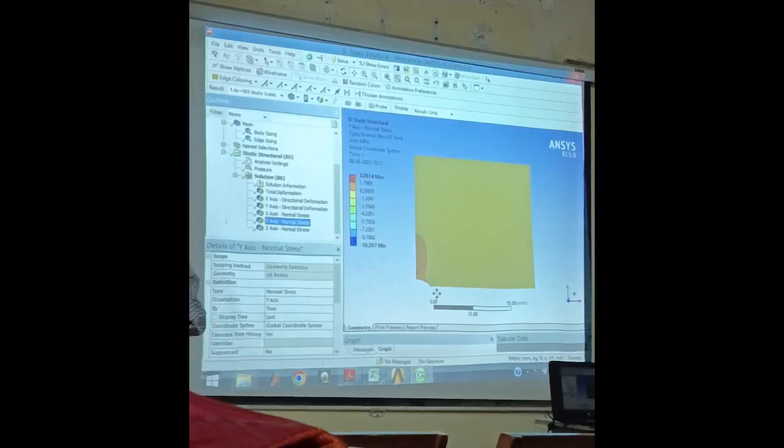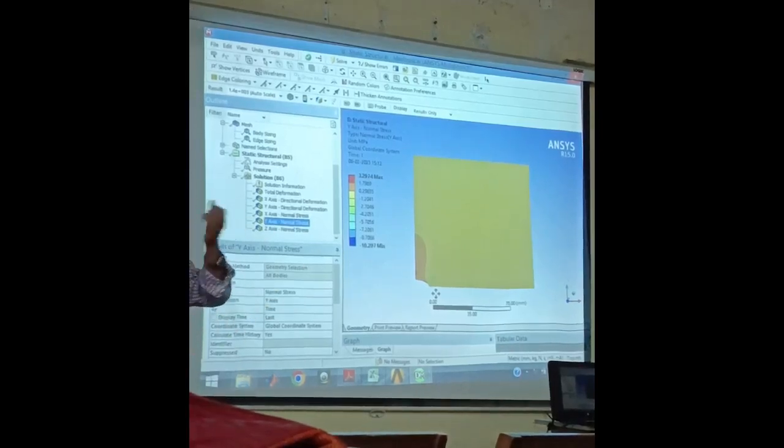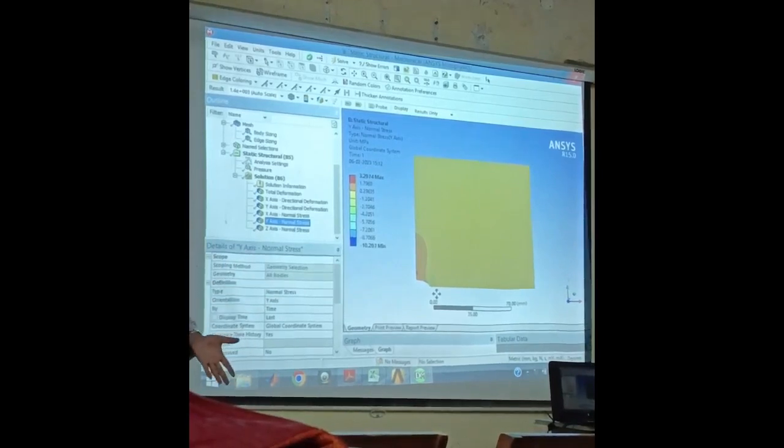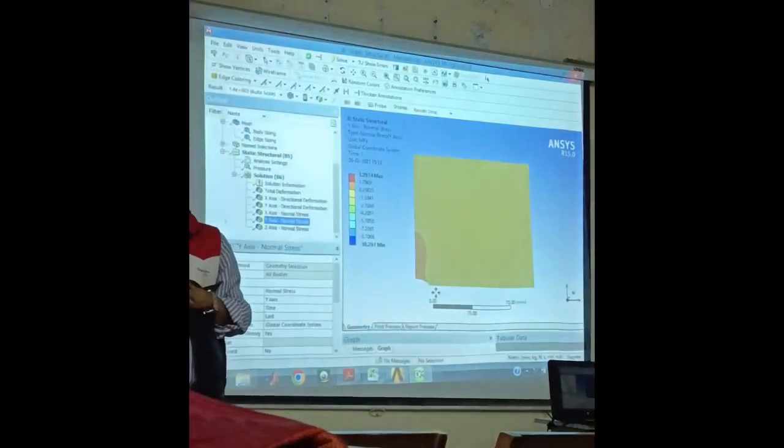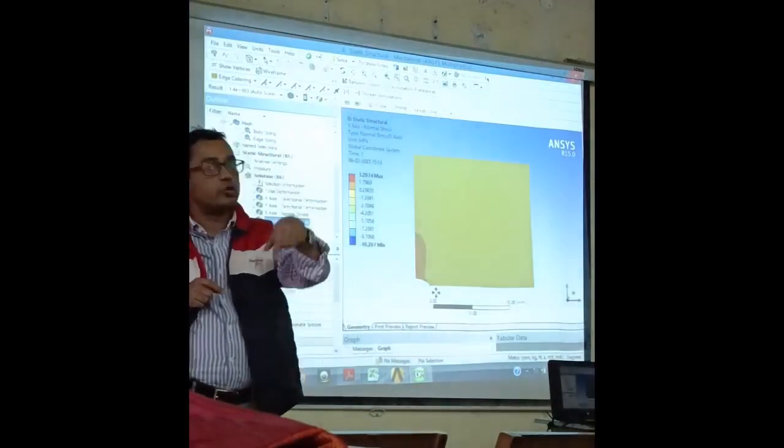Lift, the formation of the lift, aerodynamic pressure, gust, and many gas loads. But inside it is always 1 atmosphere pressure. Otherwise, human comfort will not be there. You cannot travel. In that case, two forces are active. One is axial force, the other is hoop force. Axial stress, the other is hoop stress.